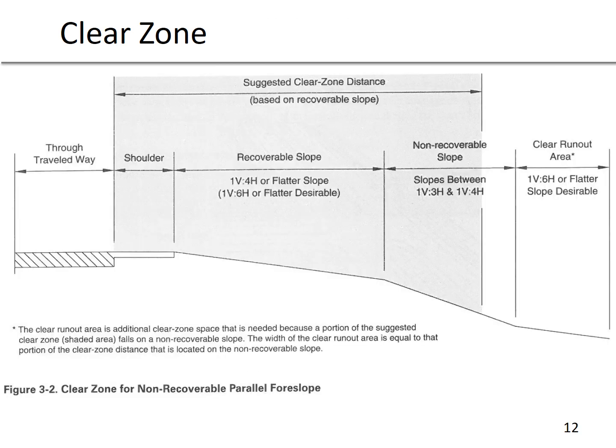And this illustration defines the 3 key types of slopes we have. Although it's not shown, critical slope is a 1 to 3 slope or steeper, and we want to try to avoid those slopes if possible. We typically will have to have some type of treatment if we have a critical slope in our roadside environment that penetrates the clear zone distance from the table we saw previously.